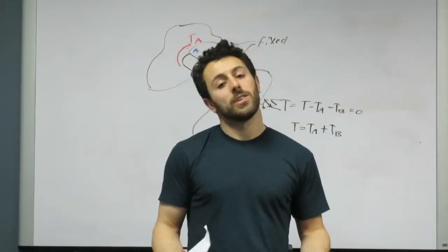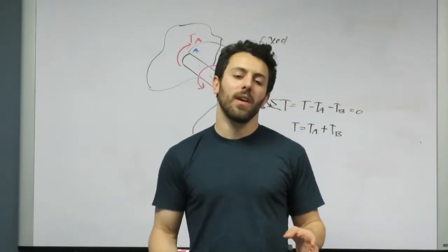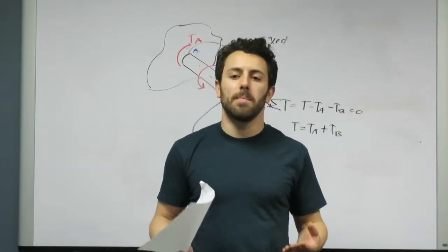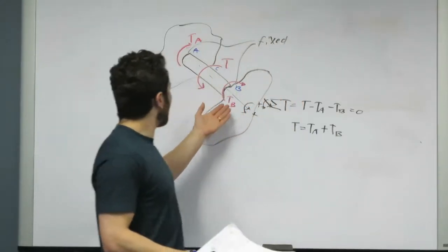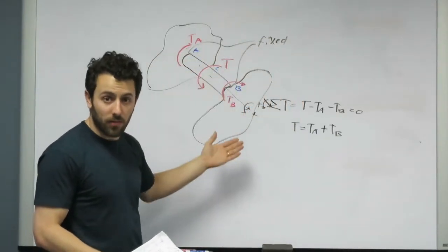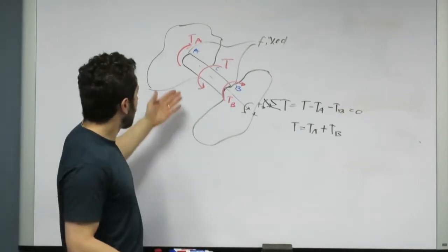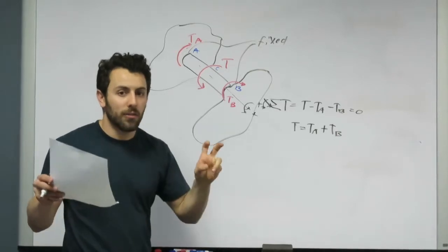We need to find the equation of compatibility. Now, compatibility is where we need to find that equation that gives the best representation of how the member under analysis reacts to the applied forces. So, if we have a shaft that has 2 points that are fixed, those 2 points being the ends, we know that the shaft between points A and B is theoretically not deflecting.